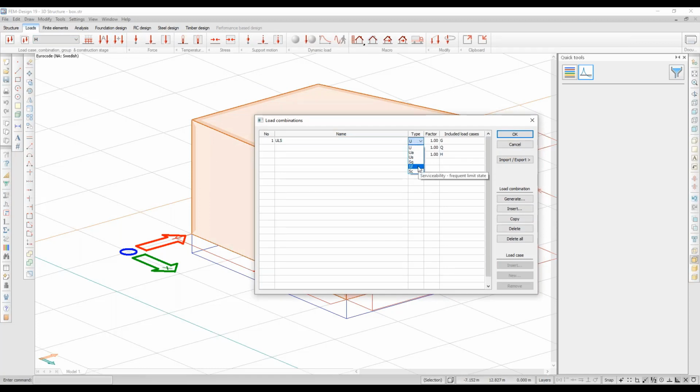Finally, when the user checks the different load combinations, they get the proper deflection results according to the reduced moduli with the relevant K-def factors. So the answer is no, the user should run the calculation just once, and in the background we consider the relevant K-def factor for the adjusted type of the load combination.